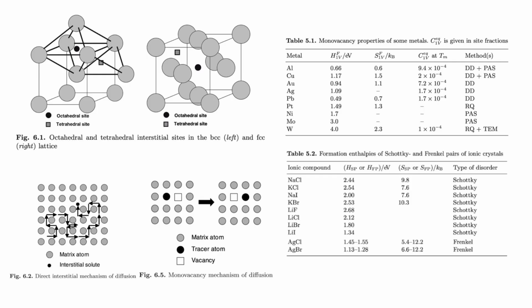At melting temperature, for aluminum, the vacancy fraction is about 10 to the minus 3, so 0.1%. At very high temperature, that's actually quite significant. A lot of vacancies were created. And for most of these materials, you can see at melting temperatures it is about 10 to the minus 4, 10 to the minus 3 range. But what about these two numbers, enthalpy and entropy?